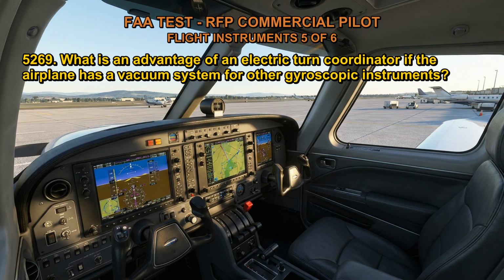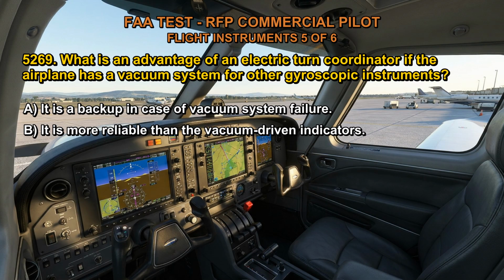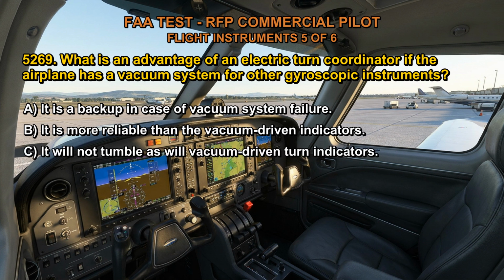5269. What is an advantage of an electric turn coordinator if the airplane has a vacuum system for other gyroscopic instruments? A. It is a backup in case of vacuum system failure. B. It is more reliable than the vacuum-driven indicators. C. It will not tumble, as will vacuum-driven turn indicators.